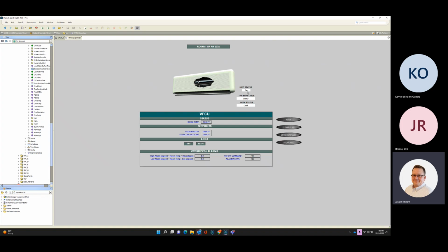We were able to get a unit status, fan speed status, and the mode status. I made it so the set points are override, auto, and set. This is one of those things where it's last one wins. You can stand there in front of the BRC thermostat, the Daikin thermostat, and manually change it there, or you can do a set.